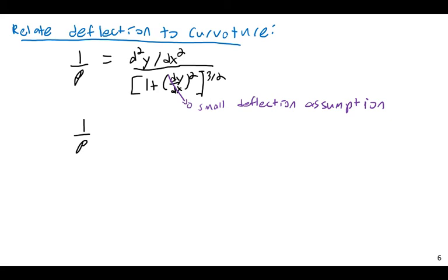But if you have a beam that is 10 feet long and your deflection is a foot, your beam has basically already failed. You are well outside the elastic range, probably past the point of rupture. So as long as we're using the elastic assumption, this is a perfectly valid assumption. If we're doing something really insane, like purposely loading beams beyond the point of rupture, then maybe we'll have to use a higher order analysis, but for this, it will suffice.